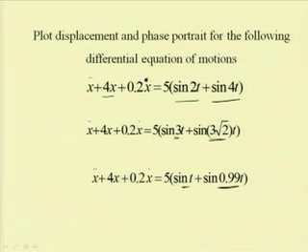But in the second case, as the ratio is an irrational number, that is 3 root 2 by 3 equal to root 2, one can get a quasi periodic response in the solution. In the third case the response will be aperiodic, or one can get a beating type of response, as the frequencies are very near to each other. This is 1 and this is 0.99. So, one has a beating frequency of 0.01.